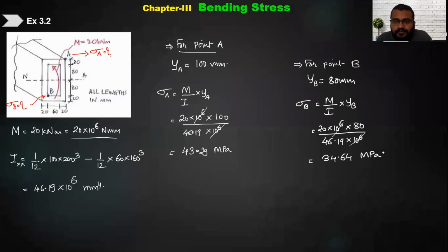No, sir, from the sign, we are rotating it. So you can see there the bending moment has got some direction. वहाँ पे देखो bending moment का direction upward, beam को upward bend कर रहा है. तो beam को अगर upward bend करेगा तो ऊपर का layer compression में जाएगा, नीचे का tension. So therefore A point is upward above neutral axis, so it will be in compression. So you can write down C for compressive stress, and T for tensile stress.